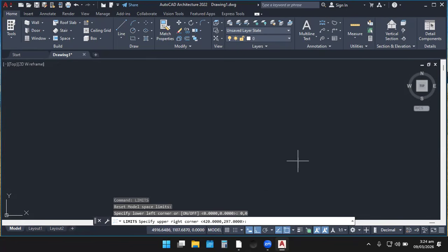So now we are going to enter. We want to use a portrait paper, so the dimension we're going to consider in this case is 210, 297. We are adding another 0 to it because we want it to be quite large, so that is 2100, 2970. That is just the dimension of a simple A4 sheet. So I click enter. And then what are we supposed to do next? We click zoom.